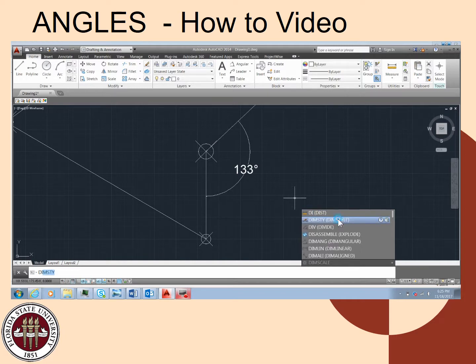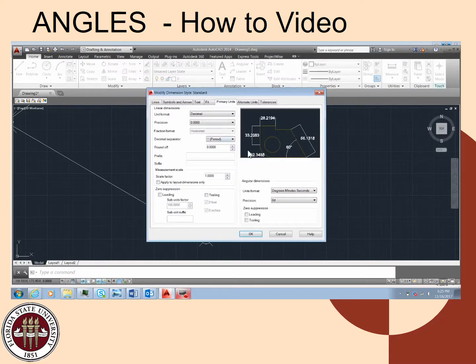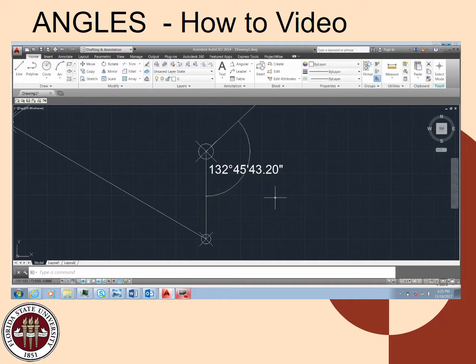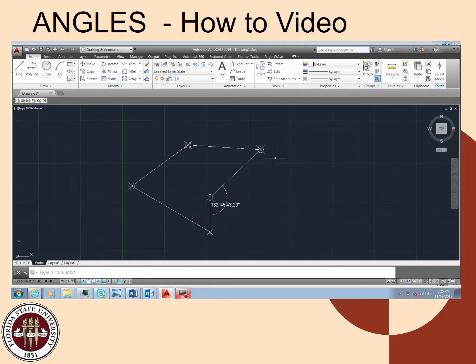So I'm going to go back to dim style. I'm going to modify the existing style, and I'm going to change the precision to something more realistic. Let's hit OK, and it's going to change the enclosed angle into degrees, minutes, and seconds, which is typical of what most surveys would look like. Okay, I'm just going to repeat the same thing. Angular dimension.